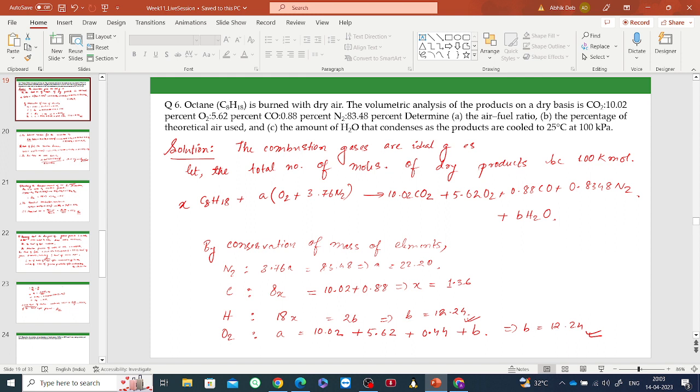at this specified state of 100 kPa and 25 degrees Celsius. This value is totally determined with respect to the assumption that at 25 degrees Celsius and 100 kilopascal, the stable elements like carbon, hydrogen, oxygen and nitrogen have zero enthalpy of formation. And for carbon, since it exists in many different states, graphite is taken as the stable form.